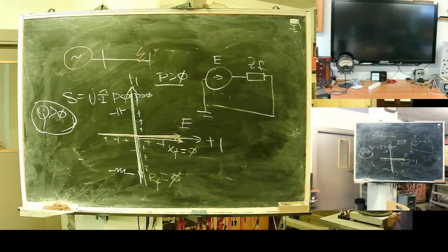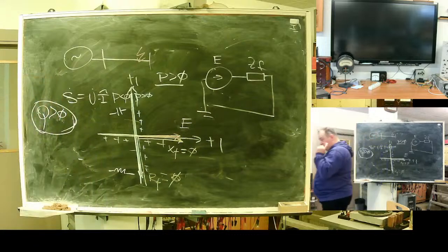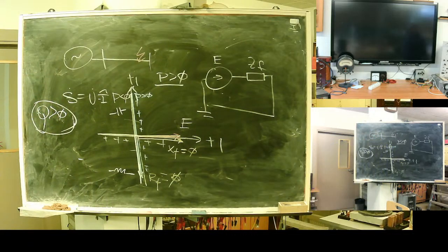We start thinking about reliability. For reliability, a three-phase fault is possible, but it's rare. Usually, we will start from phase to phase. I'm not talking about ground faults here. It's a distribution network with isolated neutral. Ground fault is a different story. I will speak about ground faults.